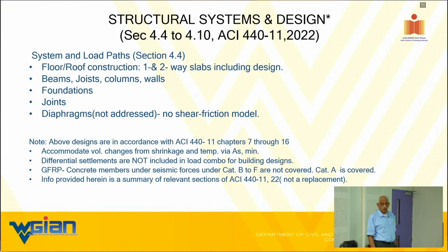Another unknown: differential settlements are not included in the load combinations for building design. What's a differential settlement? Unequal settlements, especially if you have subsidence-type problems. I think northern India has more subsidence along the Himalayan region than southern India, where you do not have a whole lot of underground mining. Also, because of drawing off so much underground water, you're getting sinkhole problems too.